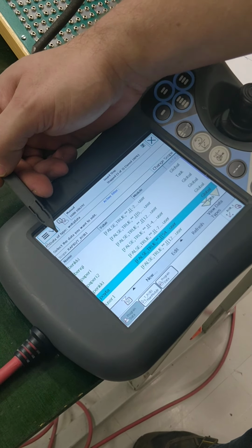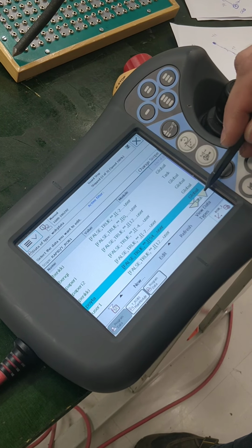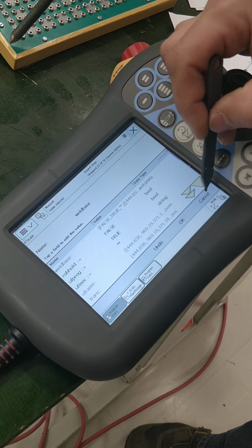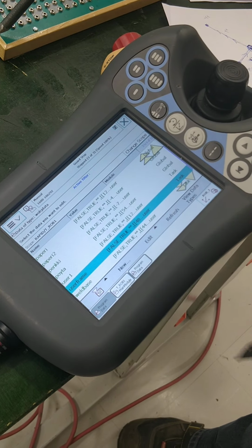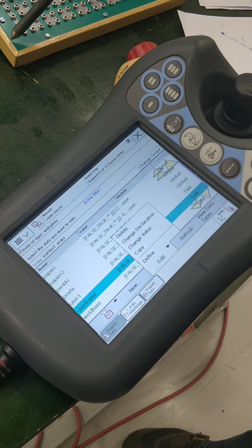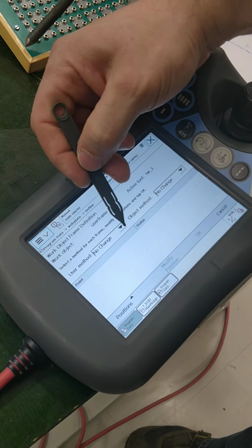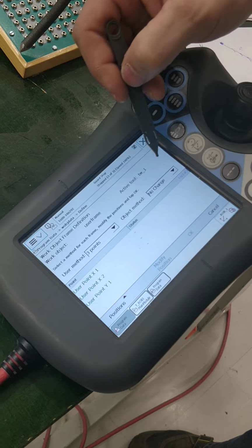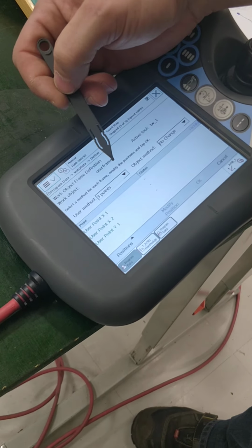You see there is a little text in the upper corner. And now we have to find your user frame. It should be that one. Yes. And now you define that user frame, which is at the wrong position and wrong place. I have to go back to edit and then go to define, and now I pick that user method to 3 point. There is also that object method, but we don't want to change that object method for now. We only want to change that user method.